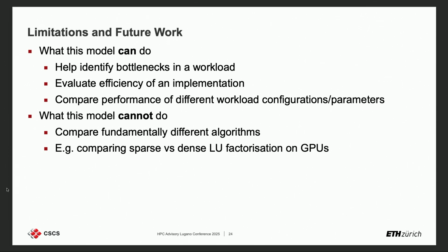It looks like you're melting the GPUs. But of course, if your system is sparse, it's much better to use a sparse solver, which is way less efficient, has way uglier or less impressive metrics, but is still way faster because it is a fundamentally different algorithm that makes use of additional knowledge of your problem. So again, you still need to pay attention and ensure that you're doing an apples to apples comparison and not just comparing two fundamentally different things that are not comparable.